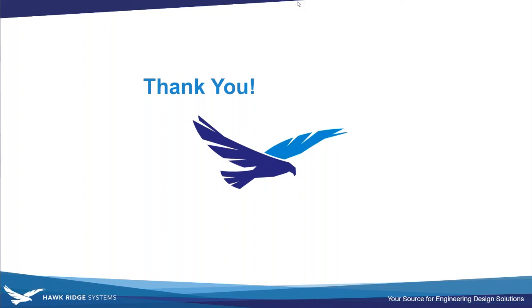If, for example, there's different features on there, but the part itself should be a single body. So hopefully that makes sense. Again, if you had modeled the chip in more detail than that, at a certain point you might decide that you just want to model the internals of the chip and then put the actual materials on each of those bodies. But most of the time, that's not what we see done. So if the chip has been modeled as a single solid, that two-resistor component is a much more accurate way to represent it.